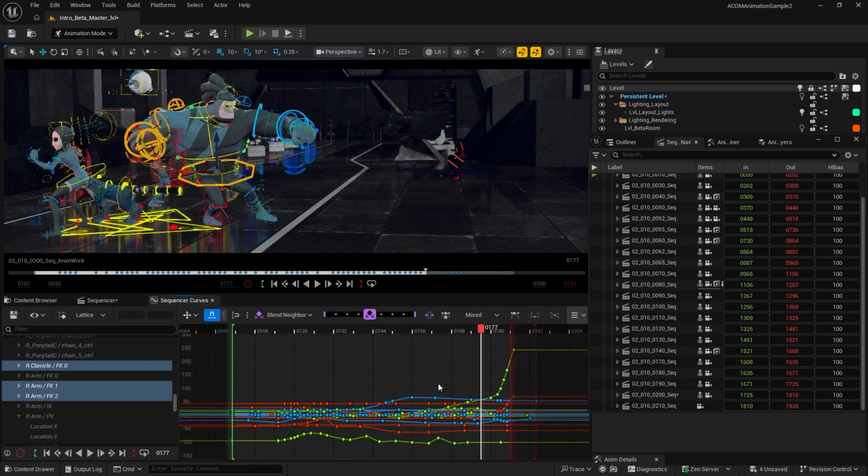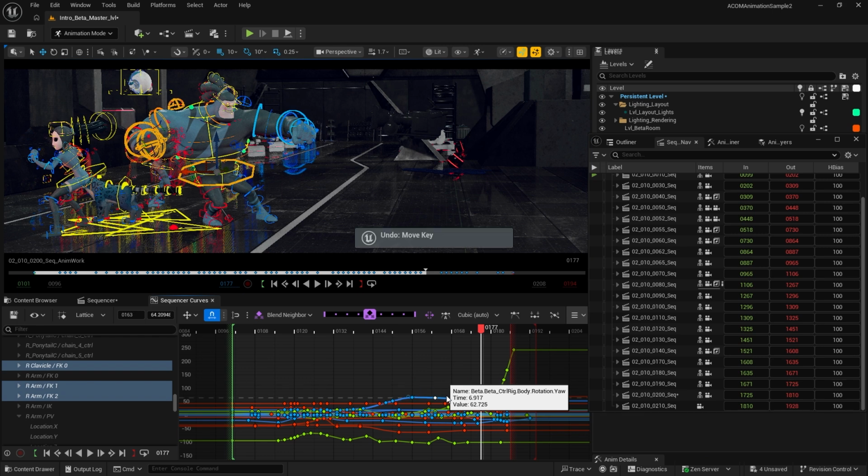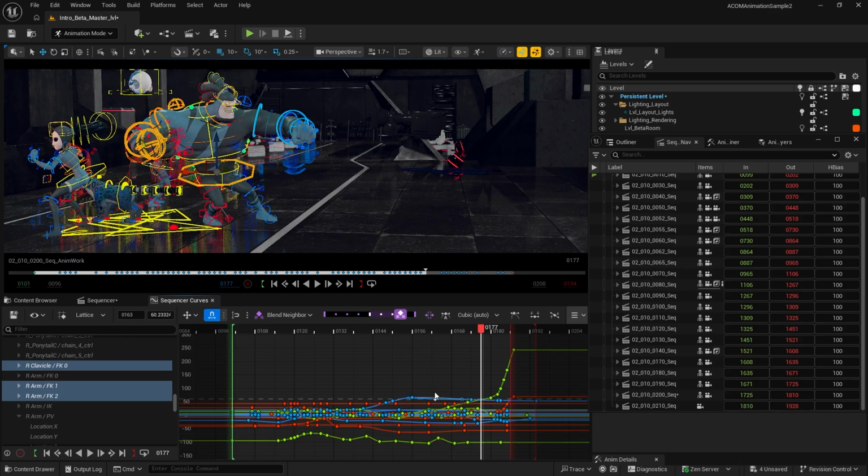I'd like to also talk about the shortcuts. If you click on one of those keyframes and just move around with your mouse, it would move in whichever direction you move your mouse. But I press Ctrl Z. If you press U and then the left mouse button, you see that only the tween tool is activated. So the selected tween tool, blend, is enabled.